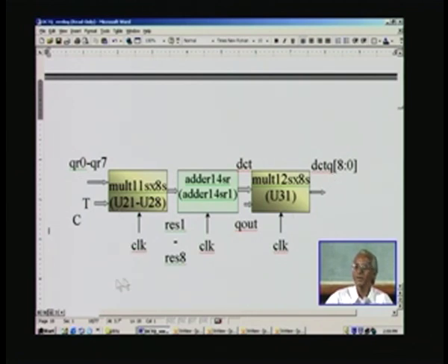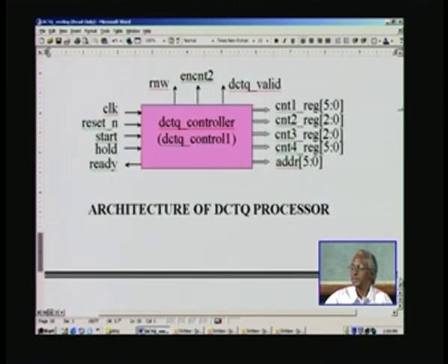So, every clock the whole thing is pushed one after another, you have seen just now the entire data flow, and this is what we meant by pipelining. You remember we have covered, while designing the multiplier, what the concept of pipelining is. Now, we should appreciate it better when we actually deal with an actual design such as a DCTQ. So, we have seen 45, we also need it at intermediate points, we will come back to this later on. So, this completes the architecture which has a one-to-one correspondence with the algorithm.